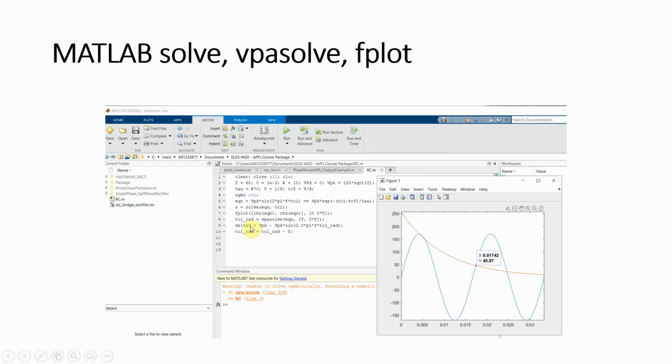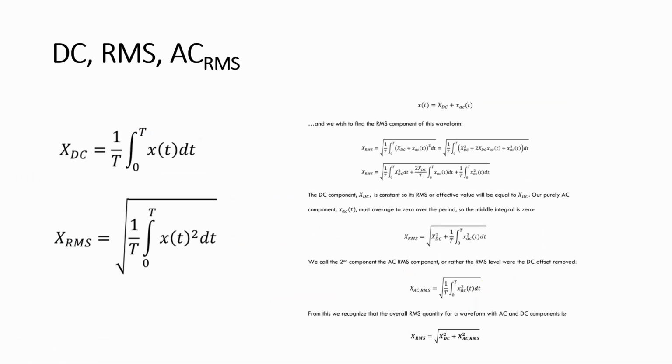And the first initial conduction angle, I also found it here. I just subtracted one period to go one period back, and this is the first conduction angle. So this is how you can find delta V, the initial conduction time, and the initial conduction angle.